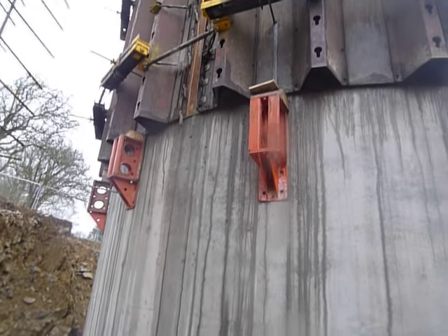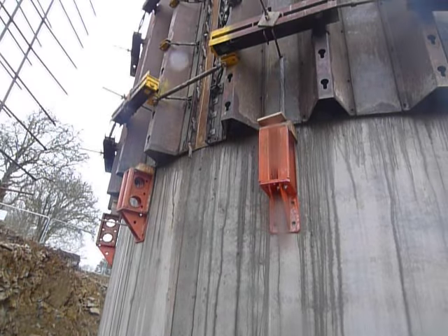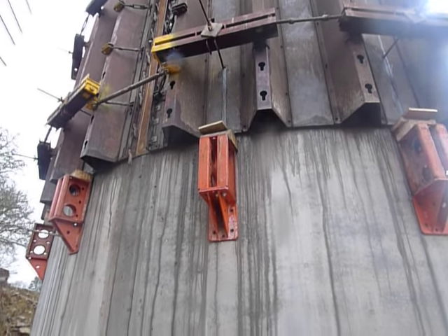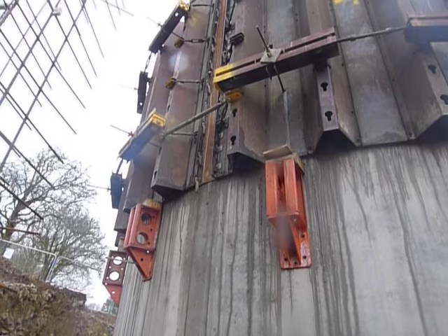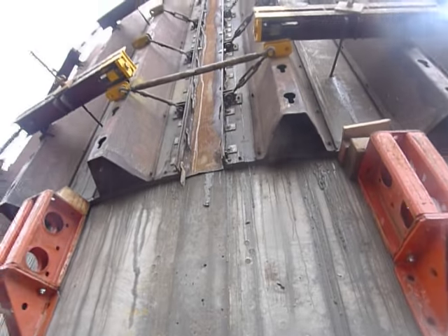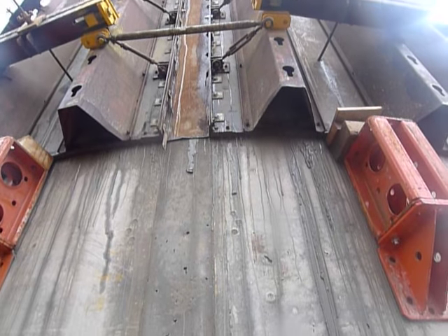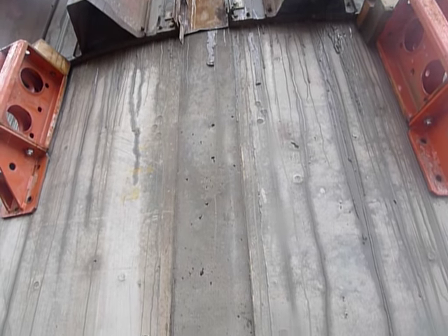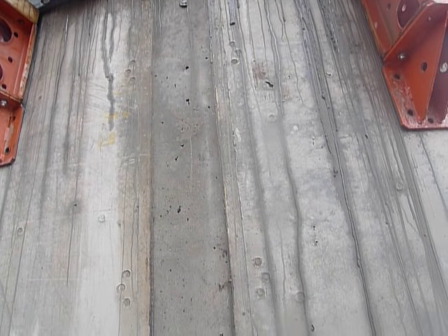One of the worries with placing the concrete too fast is that we might have had some grout loss or misshaping in the shutter. If there was to be any, it's likely to be at that point where the shutter joins. If you see that dark rib in the concrete here, that was where we did the first pour. What we noticed on this particular section of the first pour is that at the bottom of it, because of the speed of the pour, we had a very small bulge.